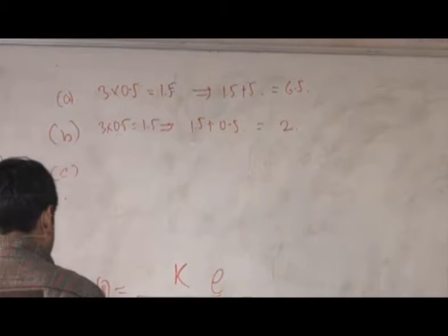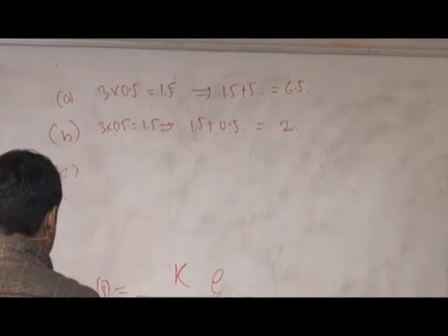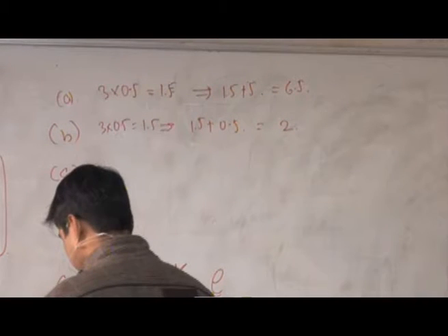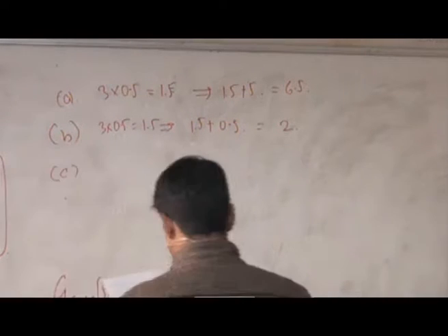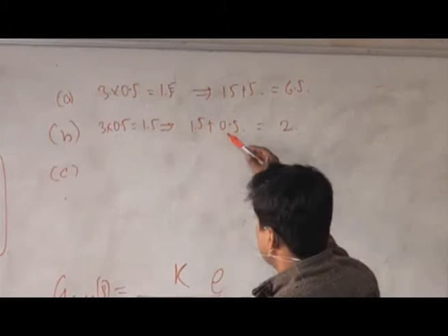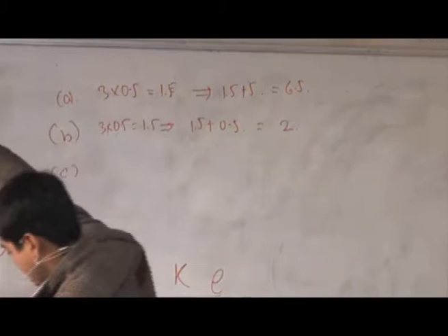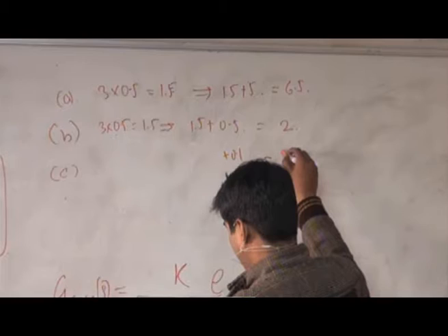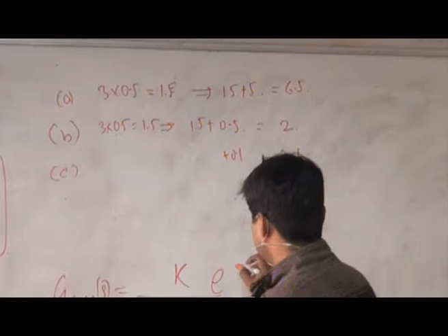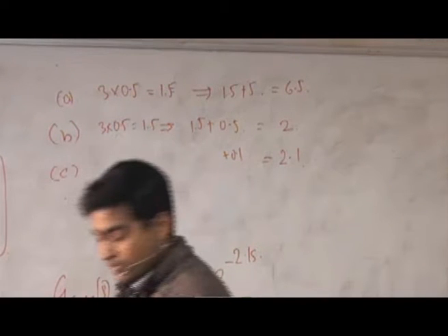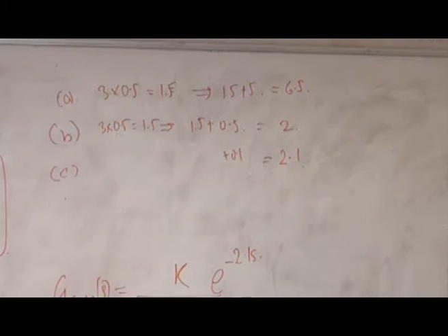The third rule says time constants that are smaller than the largest neglected time constant are approximated as time delay using the previous equation we have seen earlier. So if I sum them all for the delay, I would have 1.5, 0.5, and 0.1 plus 0.1, which would give me 2.1. My transfer function will become this one.